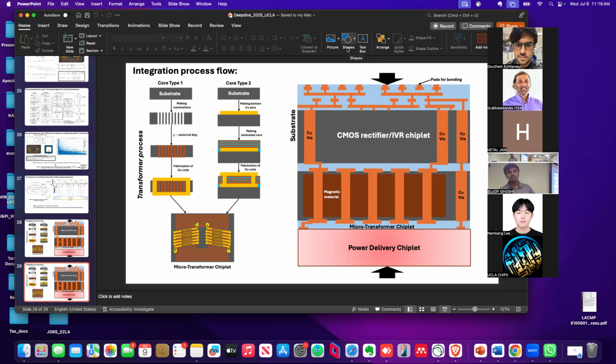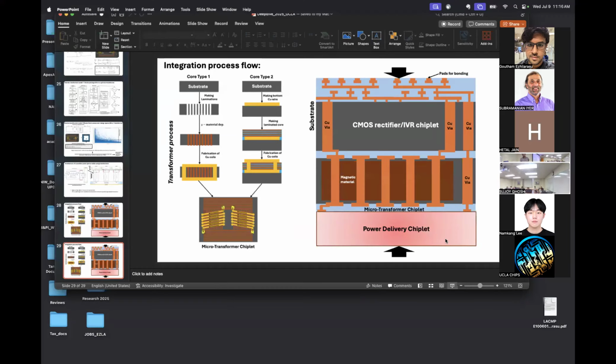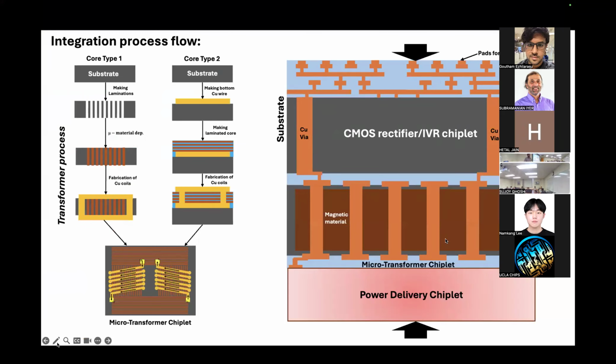Okay, I think you should actually still focus on core type 2. I know it's coming back to that. The reason being, if you actually study what the exact thickness of those layers needs to be for the material that you had in mind, for this frequency, typically the ferromagnetic thicknesses are like 100 to 200 nanometers. I know that, but each stack and the specific height you need to meet spec, I feel like that's quicker to get started with.